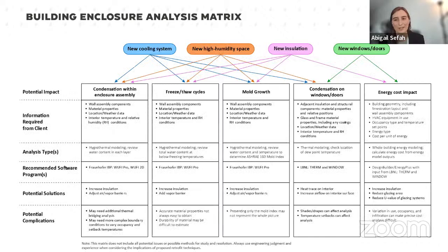Each of those interventions on the enclosure can have several negative effects on the performance of the existing enclosure and of the new assembly. Those include condensation formation, associated freeze-thaw cycles, mold growth, condensation on windows and doors, and they can also have an energy cost impact.